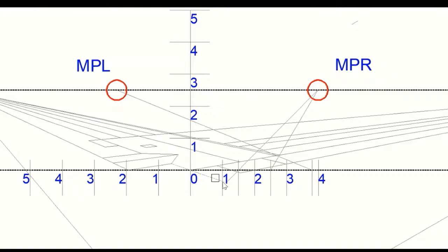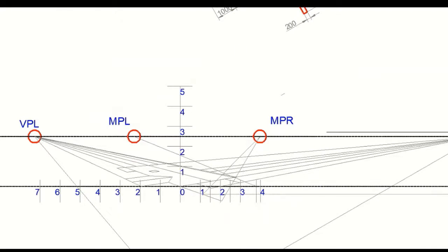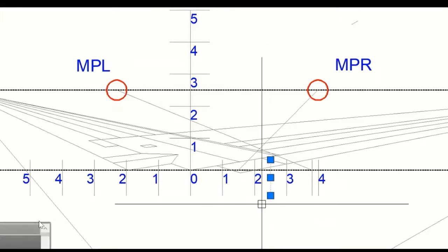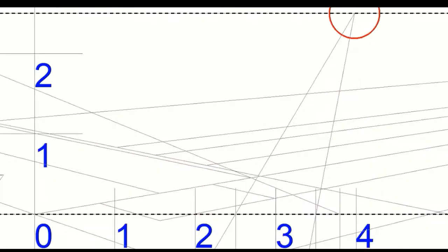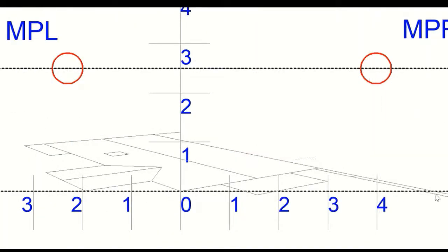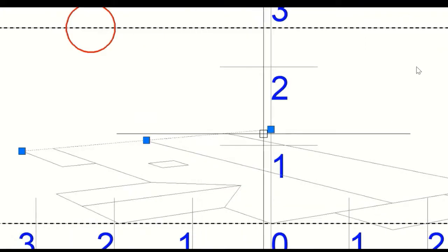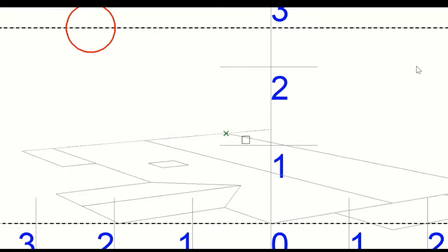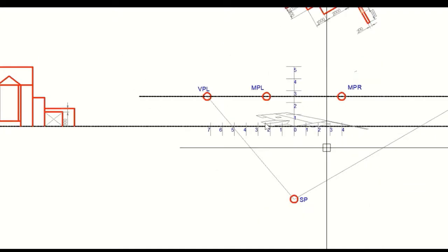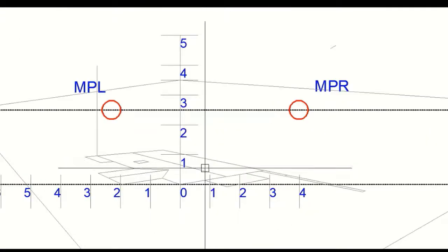This is 1 meter length, and again 1 meter, but from here it is 1.5 meter, and then 1 meter. So this is how I have created 1 meter, 1.5, and 1 by taking the length from this axis and joining there. So this whole plan has been drafted using the measuring point method, and now we will take the heights.